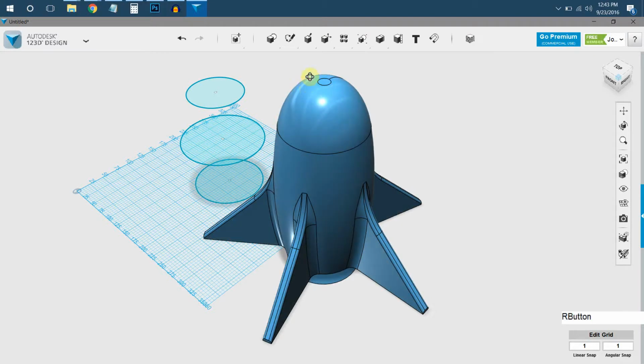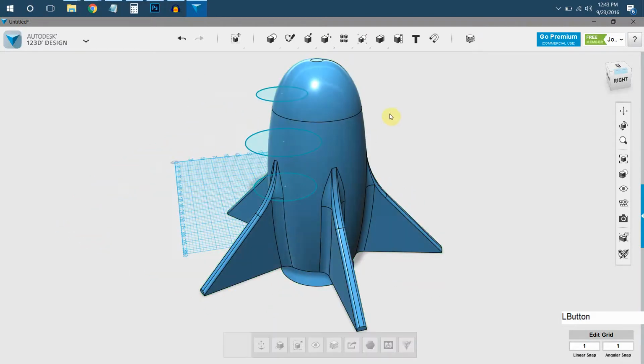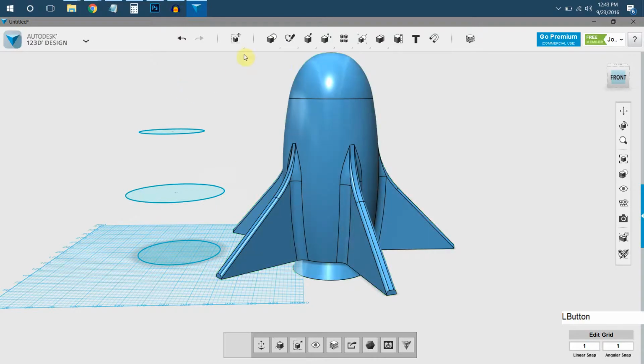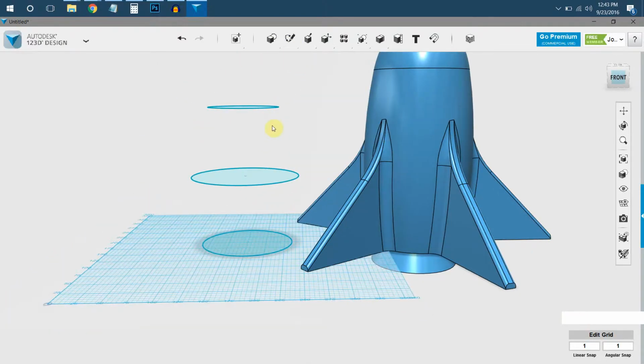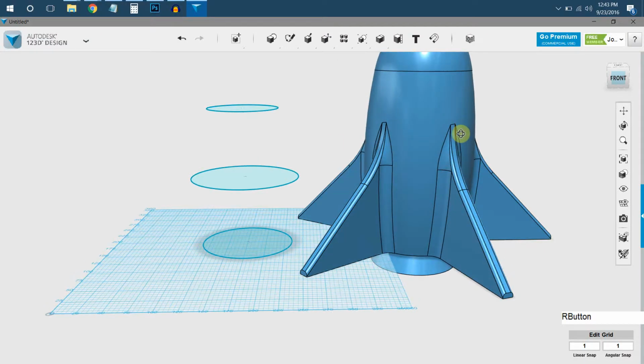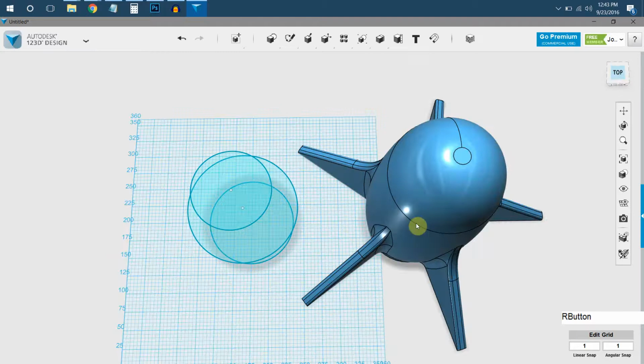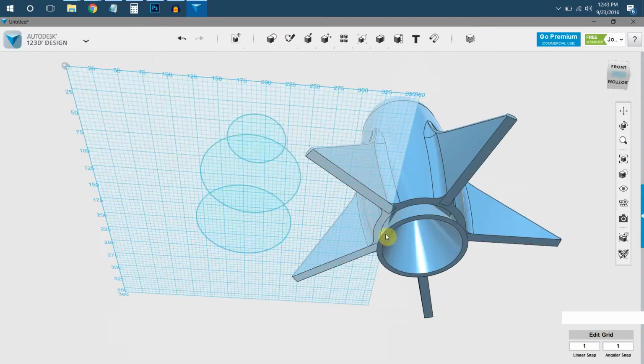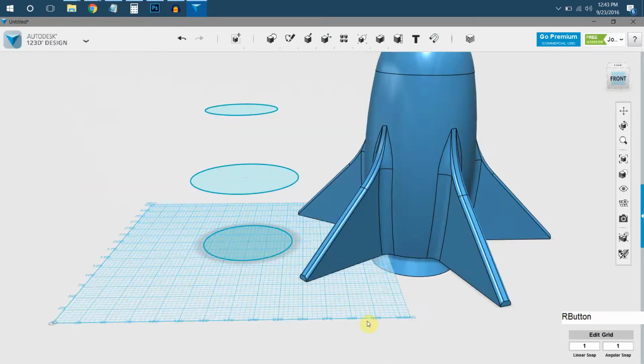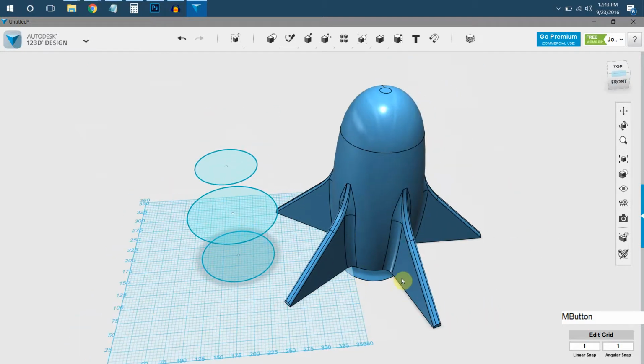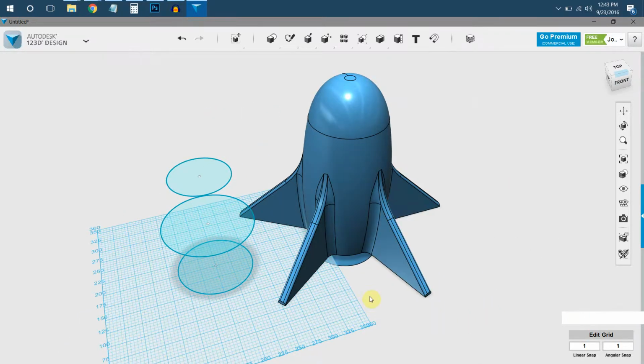But basically, when orienting for printing, I always like to go into either the software we use at Hatch or just here in 123, and I explain that if you're printing, it goes in a zigzag way like that, layer upon layer. So I explain the best way to print this is standing upright, because the printer is more accurate going in a circle on a flat axis than if it's standing up, stuff like that. I don't want to get too much into detail on it, but that's pretty much it for this tutorial.